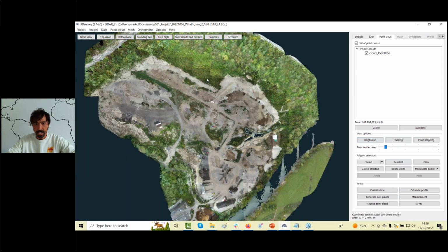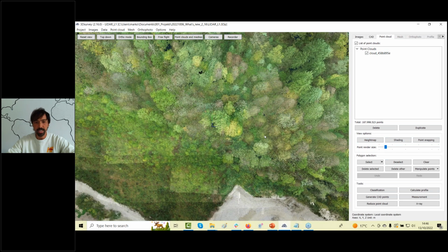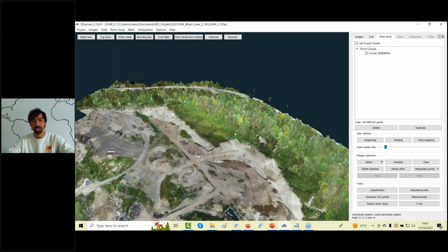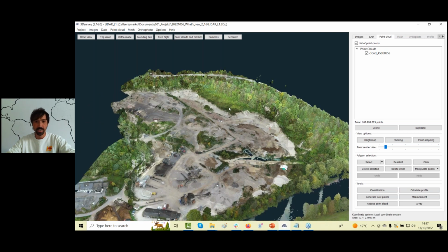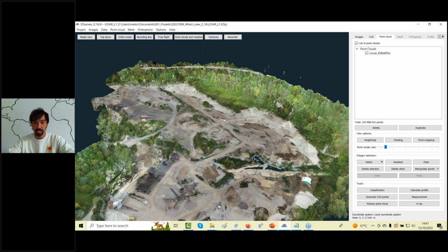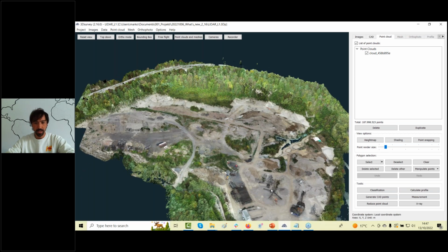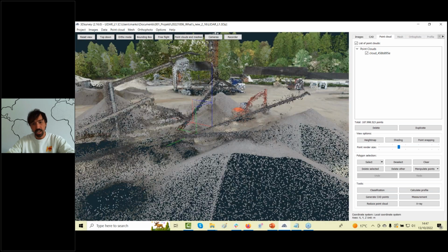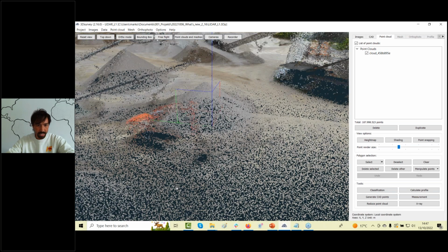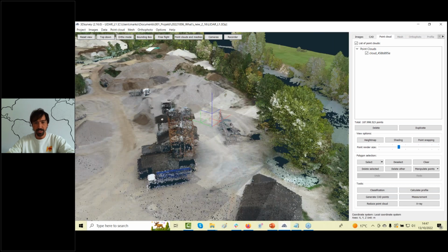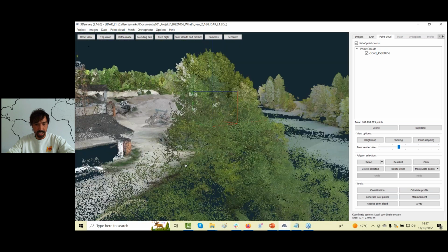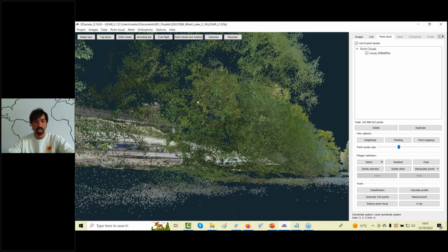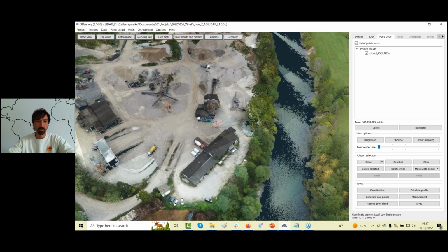But nevertheless, the idea is to get terrain points under the trees also with our classification. That's why this was created with a DJI L1 LiDAR scan. In this case, we have 190 million points, quite a lot for this kind of area. The detail of the LiDAR point cloud from the L1 is not bad, but photogrammetry is, let's say, 5 times better for open areas. But if you need points under the trees like here, you would probably need LiDAR in addition, and of course then good software to classify it.